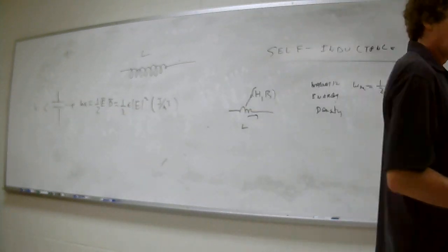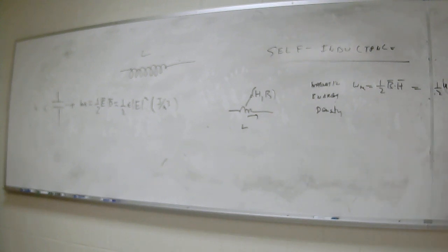Well, if you wanted to know one way to calculate the self-inductance, if you integrate the magnetic energy density created by that current over the volume that exists, so this is over the total volume, it would be equal to 1/2 L i squared. You'd have to calculate the current actually to cause this magnetic energy density.